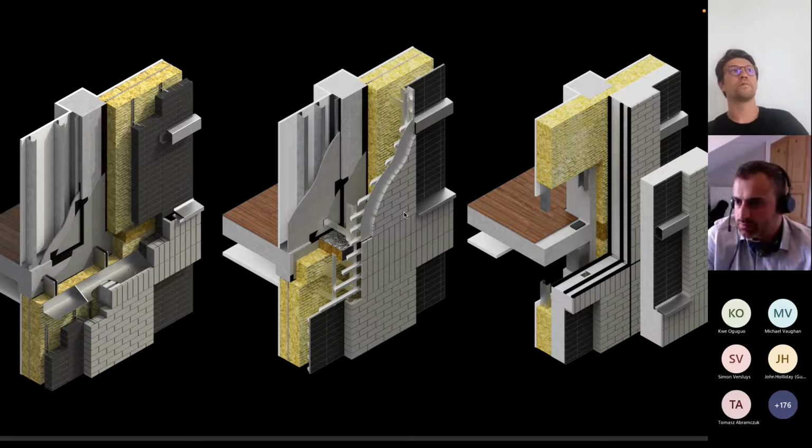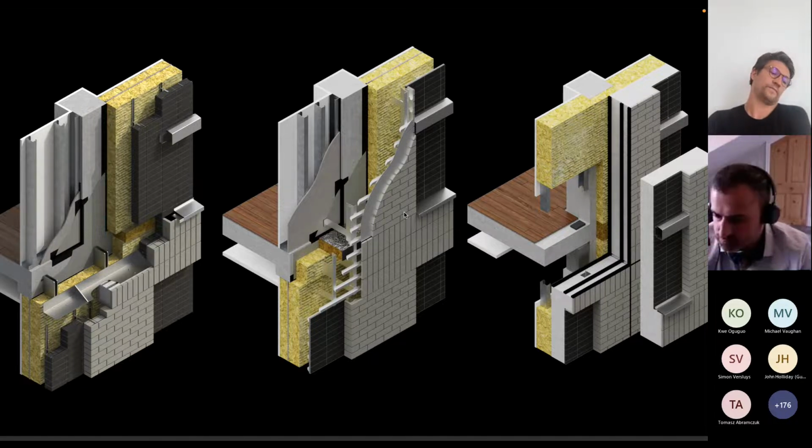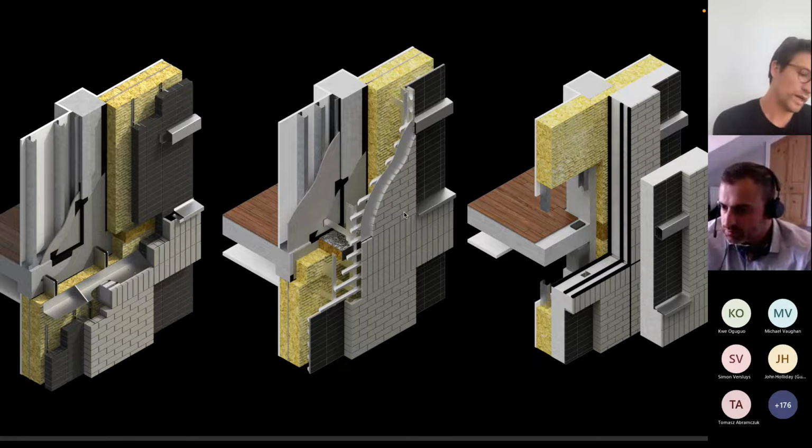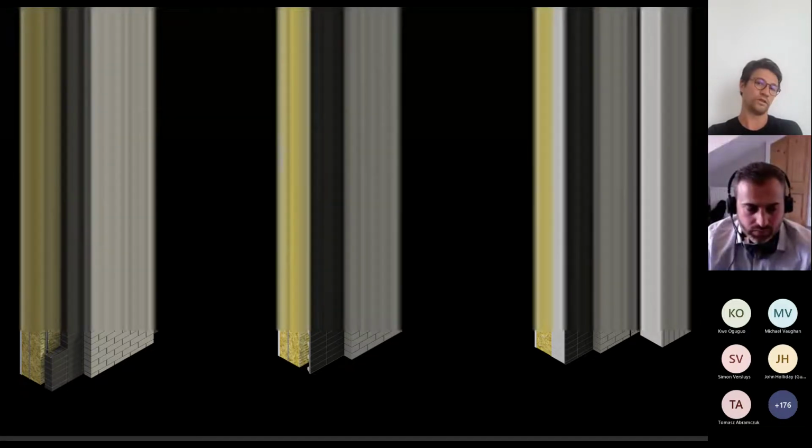for example, Corium brick slip would not be able to achieve some of the natural brick looks, because it's a terracotta tile. Effectively, it's a ceramic tile extrusion. Whereas the other 2 would be able to achieve most of the outlook. However, I personally really like Corium for its engineered way of installation, and I think it's probably the oldest in the market, and has all the relevant certification.